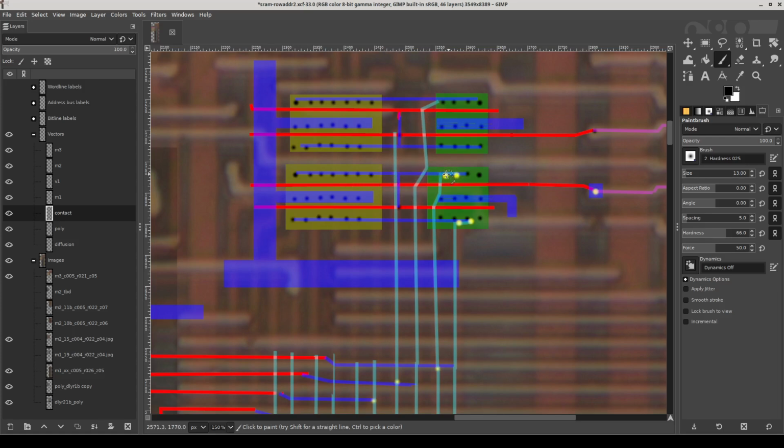And if we then follow that onto metal 2, we can see that this left line here is inverted of this. But then also, that same metal line continues down to a second inverter here, and this inverter then has the output on this metal 1 line here, which couples up to this metal 2 line, and goes here. And so we can confirm that these 2 lines are in fact being driven as essentially a differential pair. One is always the complement of the other, and they're also essentially a differential copy of this signal here.